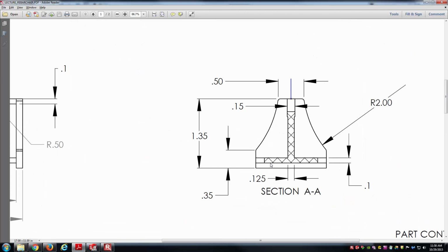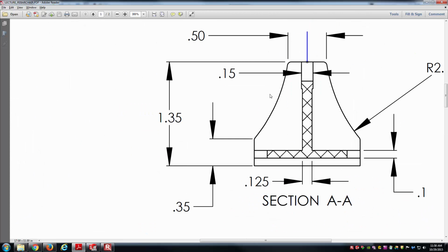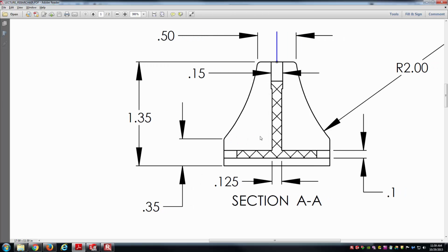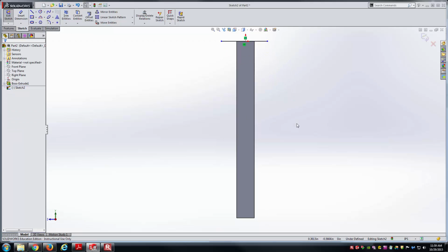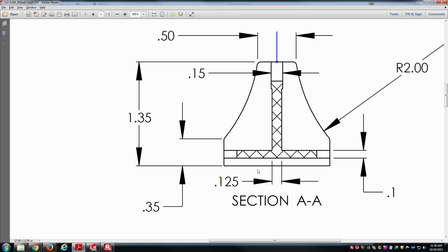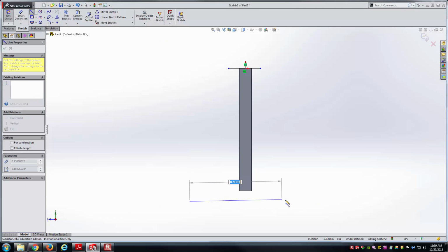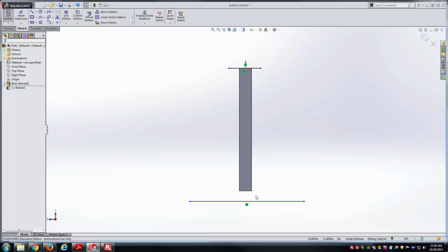As far as what the geometry is going to look like on my sketch, it looks something very similar to the outer profile of the right view here. And this one I'm going to actually remove the rounds off, and I'll wait and I'll apply those as a feature at the very end of my part. And so with that being said, I'll have a horizontal line here. Notice the horizontal line is going to be at the very bottom, or excuse me, past the bottom here.